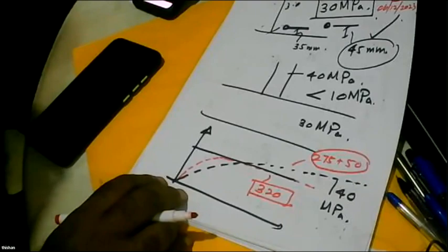Now 2 years have gone, you have cured it properly, you had fly ash to continue the reaction. You take a core and see, the real concrete can be ranked as 45 megapascal cube strength concrete.